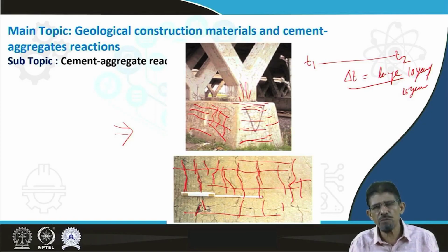Some of the mosaic structures show a very dirty appearance due to release of grains from the original concrete structure. Originally, at the time of formation or 2, 3, 4, 5 years before, the mosaic structure was beautiful, shining and so on. After more than 10 years, it started showing release of grains, blowout of grains, from the concrete structure.